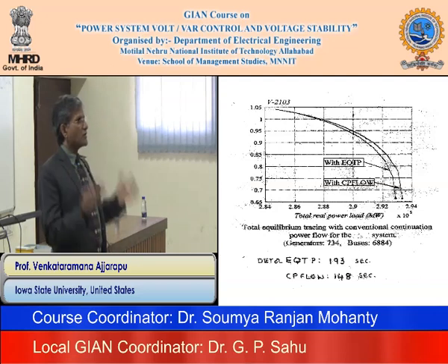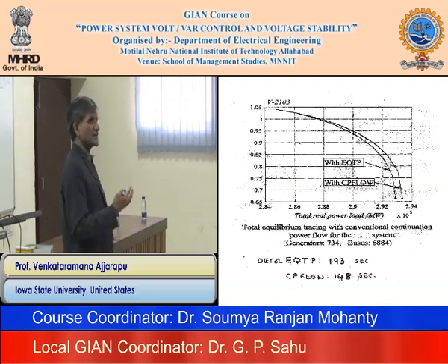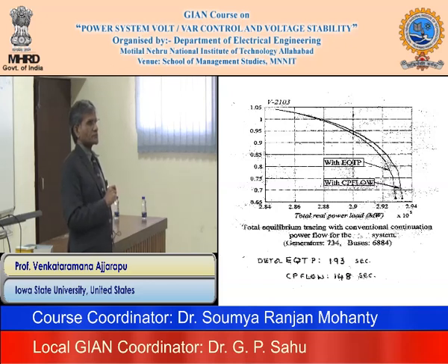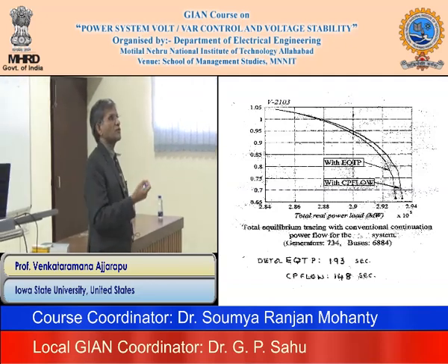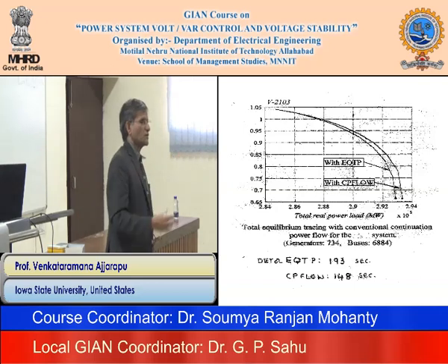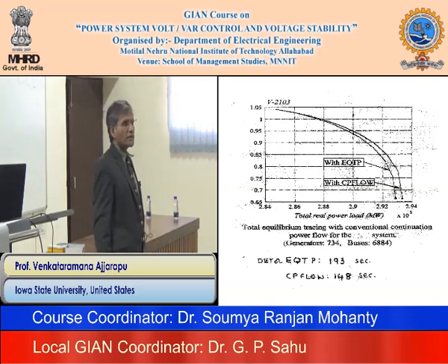So in the governor power flow, in the steady state, they actually represent the governor function in the power flow. They are first order, a simple governor, and they also represent the voltage regulator in some way. That's why I don't even need to assume a PV bus, right? So in that case, I will get a true solution for the equilibrium. Then I don't need to depend on the power flow.